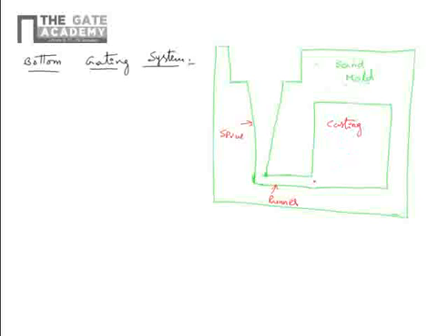This is the bottom gate because its ingate is at the bottom of the casting. This part is the ingate. This is the pouring basin, where you pour the molten metal. So here, for calculating the height for velocity, you have two heights. If you look at this, one is h1, and another one is this part.